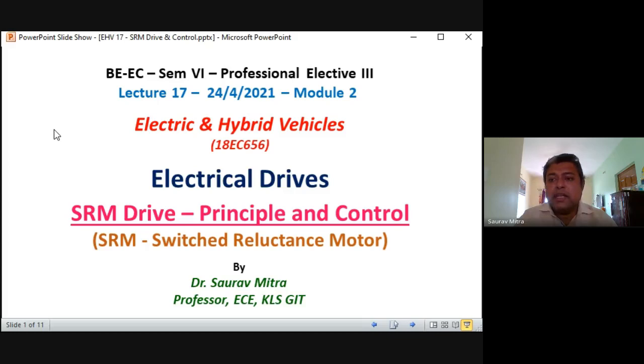The electric field we can connect directly to the rotor, as we did in the DC motor, which is a conduction type motor, and the magnetic field was being created from the same electric supply. But the BLDC motor is PM BLDC, where PM stands for permanent magnet. So the creation of the magnetic field is not the responsibility of the electricity input. That's why there is no field coil in the BLDC motor. This is the main difference.